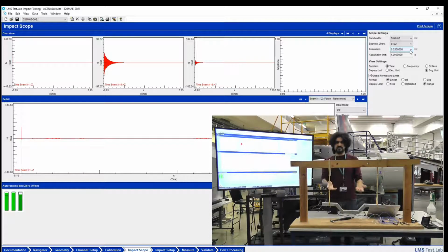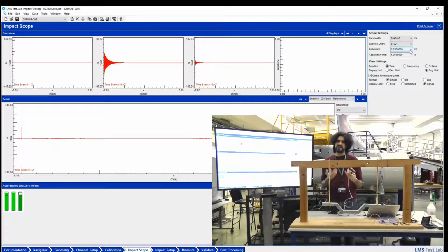This makes the test a bit slower, and it will become even slower because, of course, one strike is not enough. We want to take averages. For every point, we're going to have 3 to 5 averages. Ideally, you want 20 averages. But for the sake of this test, in order to keep it short, I'm just going to use 3 averages per point.